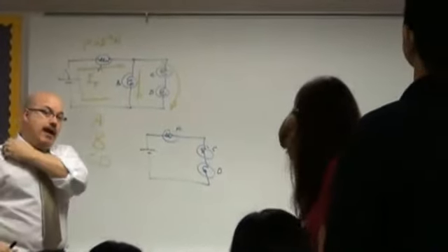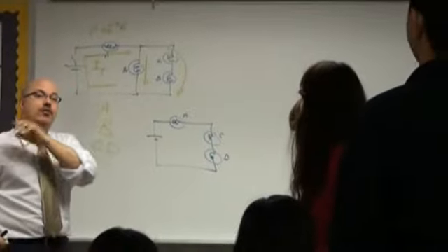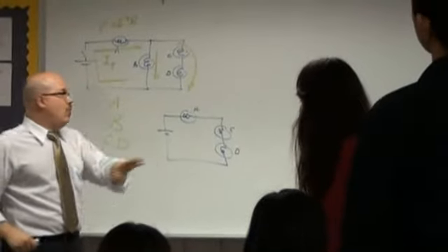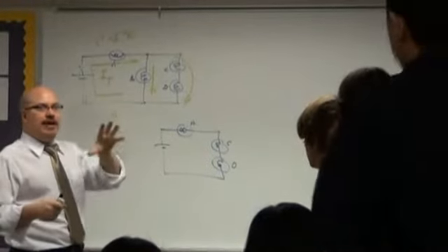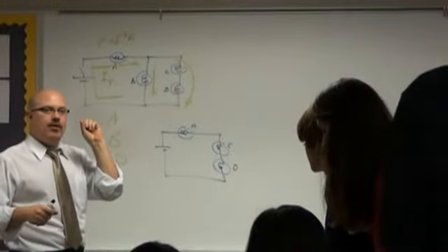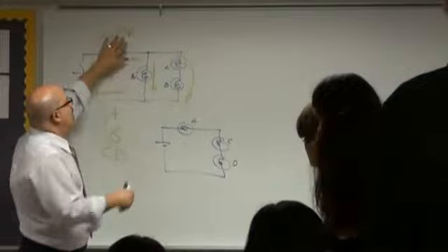All right, now, what happens to the total resistance of the circuit when I take that one out? It goes up. Why does it have to go up? I'm taking the resistor out. Just add parallel, because it gives it fewer ways to go through.